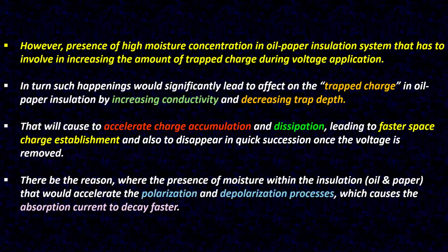However, a high moisture concentration in oil paper insulation systems increases the amount of trapped charge during voltage application. This significantly affects the trapped charge in oil paper insulation by increasing conductivity and decreasing trap depth.